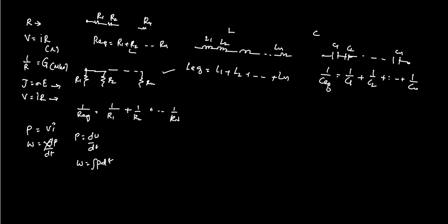What we usually do in a hurry is see capacitors in series and write the sum, thinking of series resistors. That mistake you have to avoid, the mistake we make in the examination. Whenever capacitance is in series, it is equivalent to parallel resistance.